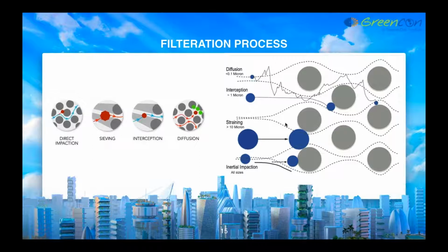And the last one, for the lowest size, which is maybe less than 0.1 micron, would move in a Brownian motion. It is so light that it does not have its own specified direction of air movement, and will tend to move in a haphazard way.